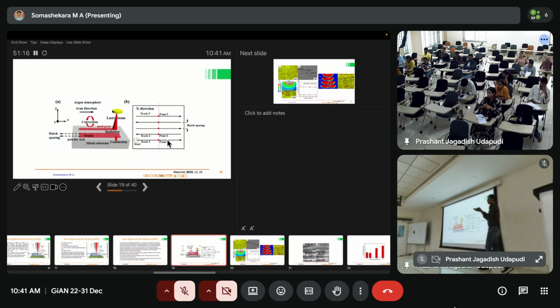That's why in a lot of metal additive manufacturing you will find a lot of warpage. That comes from your path plan. If you change your path plan, your stresses will change. Since you are generating a large-scale component, which repeatedly generates a lot of heat, you need to control your stresses and the temperatures.